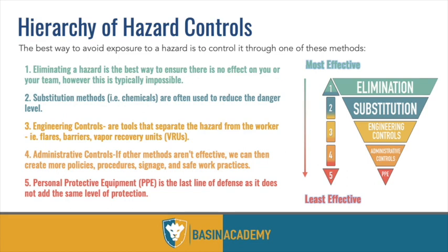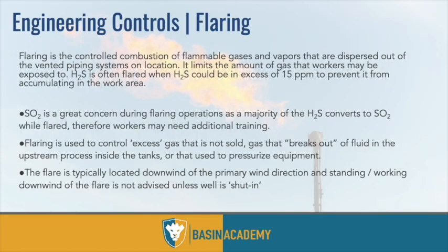So again, flaring is one great engineering control, where essentially we take any excess gas and send it to the flare, right? That typically goes through the treater, and then the excess gas is sent to the flare. Depending on the system, this may be more or less effective. If it's designed really well, it's very effective because you can even send the tank vapors to the flare, which Continental's done successfully in a lot of their wells and others.